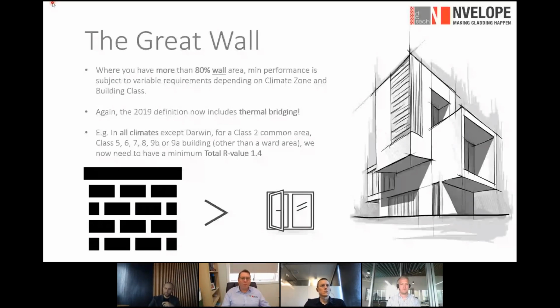Now a 1.4 R-value doesn't sound like that much when compared to 2016 standards. However, recent changes in 4859.2 and the way 2019 looks at those have altered the way that we test building products and get to the R-value calculations on wall build-ups. So we'll cover that today through the 5 walls that we're going to compare against.